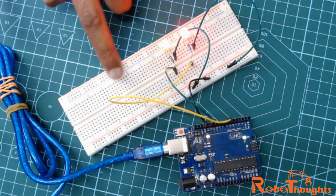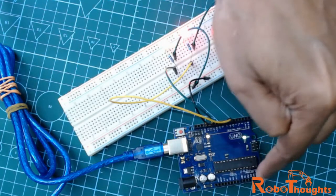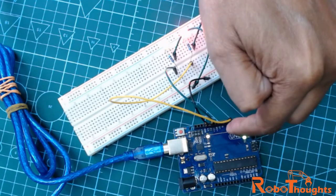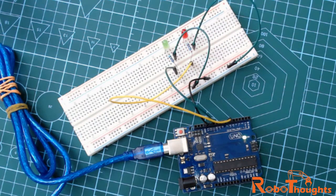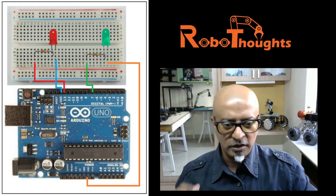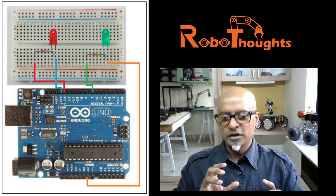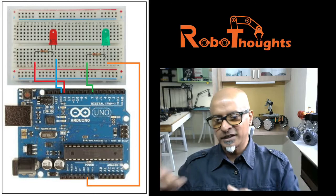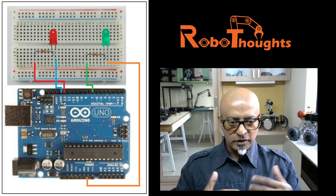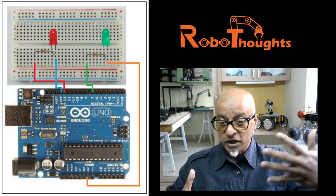Now you can connect multiple LEDs here in the row with multiple resistors and use all these available digital pins. How many ever pins you have depending upon the board you are using, either Arduino UNO or Mega or Nano. So guys, it's a pretty simple circuit. It's similar to the previous lesson what we saw, but I wanted to show you how you can use multiple digital write function when you are connecting to multiple devices. In this case it's two LEDs in the circuit, but in upcoming lessons I will show you how to connect multiple devices. That's where all this code will come into picture.